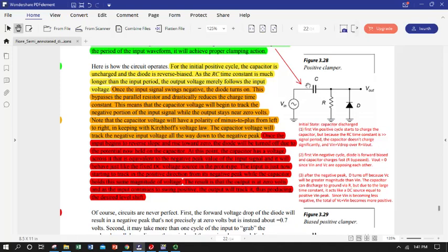So it's really not going to charge up with much positive charge on that left-hand side. But then when the voltage signal, our sinusoidal signal, swings negative, it can flow conventional current up through the diode as soon as it goes above forward bias, and now we can pile up positive charge on this side of the capacitor easily, very quickly, because the diode's going to act like a short pretty much once we're above forward bias.